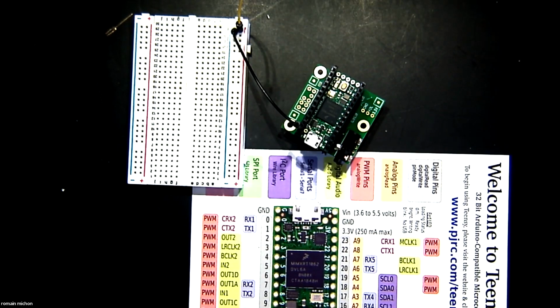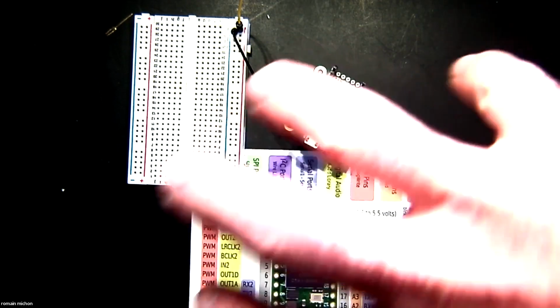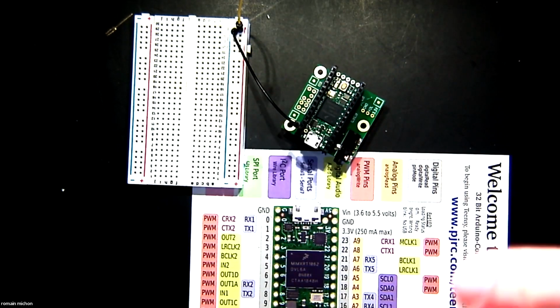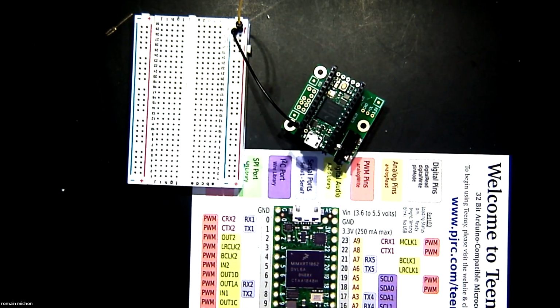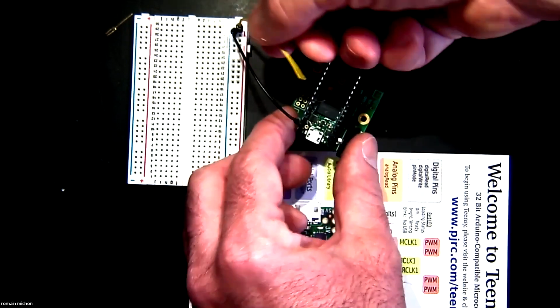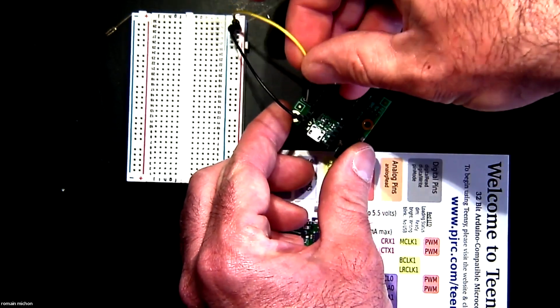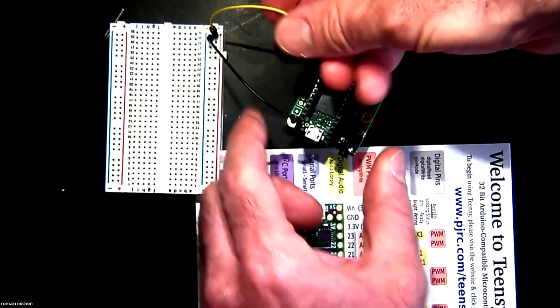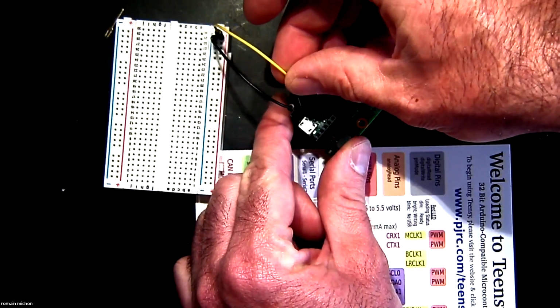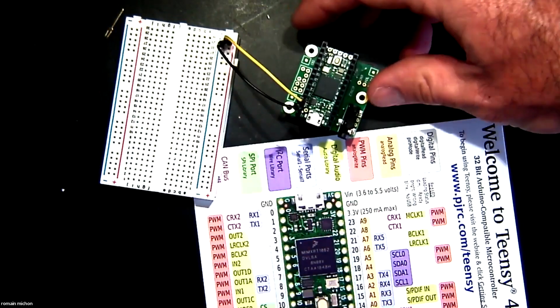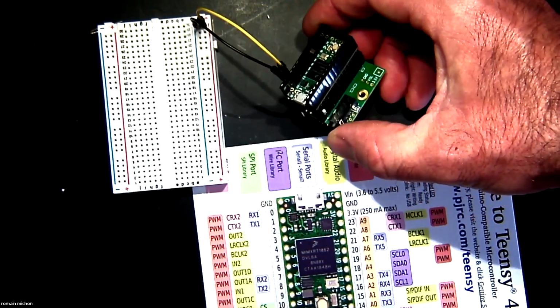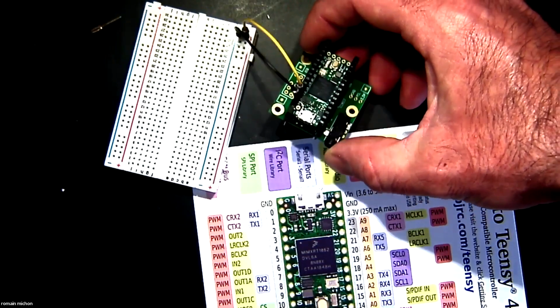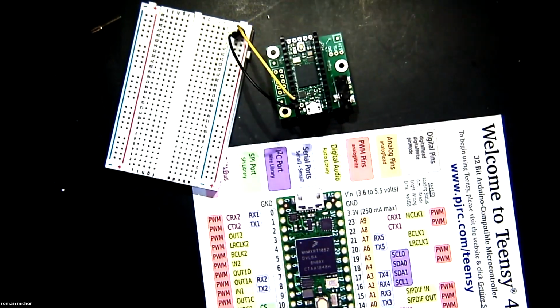Your whole electronic circuit you're going to put together on the breadboard is going to be powered at 3.3 volts, because that's what the Teensy expects. So I'm just going to connect the plus line, this one here, to 3.3 volts on the Teensy. Does that make sense? Cool.